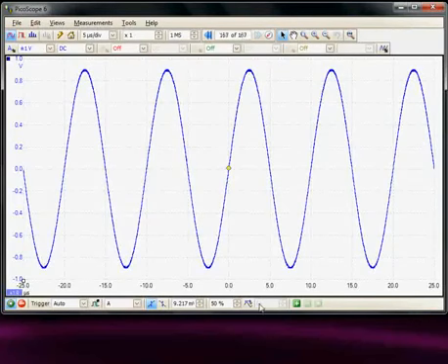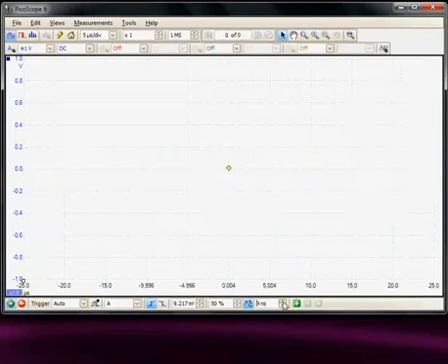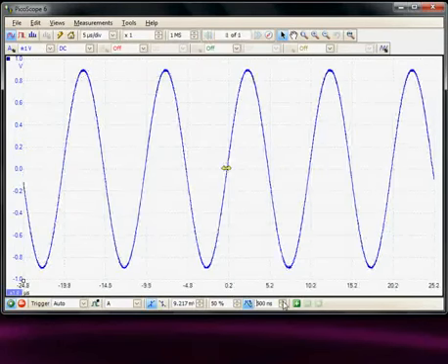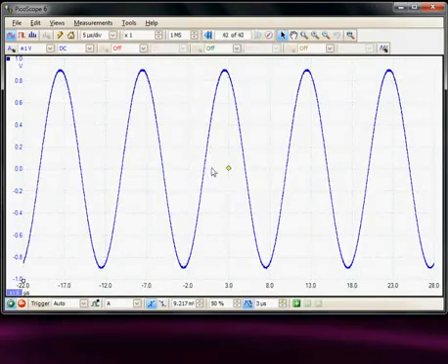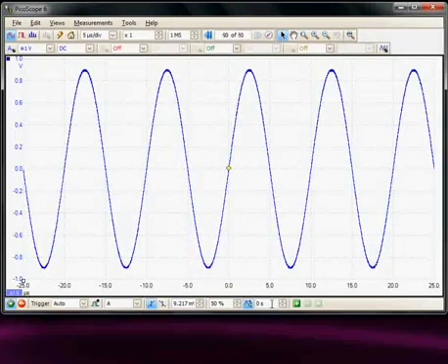The next icon is the position of the data relative to the trigger point. So we can select that, and then we can dial in delay time, and here we see now we've got a delay time of 3 microseconds, so the data is being displayed 3 microseconds before the trigger point. Again, I will return this to the default position.